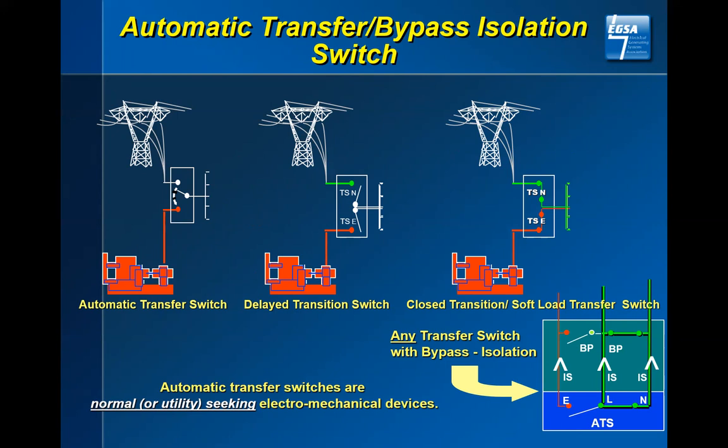They may have purposes for this. Your generator set may be large enough to run everything, but it does not have the ability to start everything. Another reason may be when you drop all of that load back on a utility, many utilities have what is referred to as a demand charge, a ratchet.